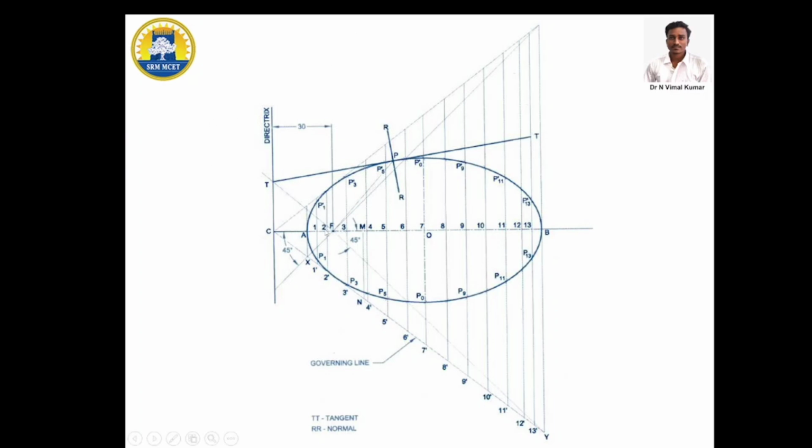From this 20 mm we need to make an angle using the protractor from the vertex point to the straight line. You can cut an arc of 20 mm from this center point to this arc point. You need to draw one straight line.